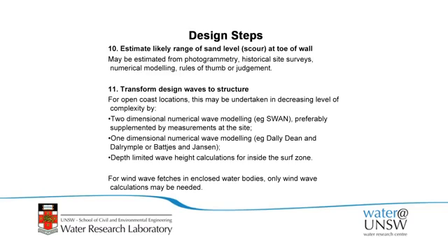So once you've done all the steps before it, it's transforming the design waves to the structure. You might have an 8 metre wave out in the deep ocean and a 1.5 metre AHD water level, but the waves are not going to be that big by the time they hit your structure, and I'll show you some examples of that soon.